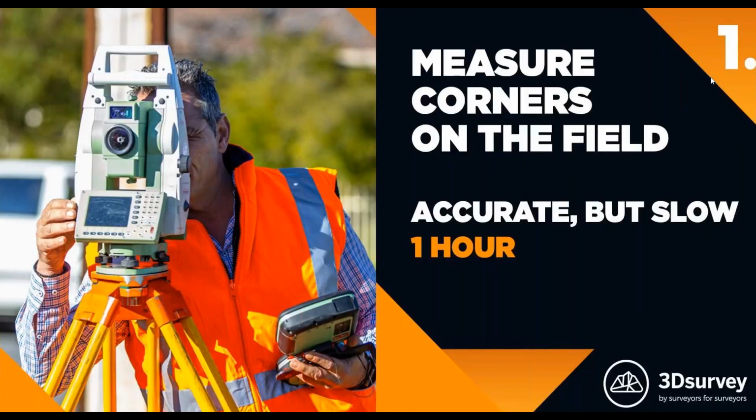Right. Now, how we measure building corners. The technique I'm sure all of you are using right now is to map them with a total station. Either we use the laser on our total station to measure them, or we have someone signalize them with our measuring stick and we measure them.